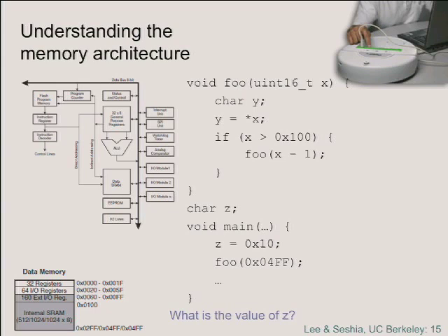We only have 1K of memory, though, in this architecture. And we've done a recursive call at least 100 times in hex, which is big enough to overwrite the memory. You're going to get a stack overflow. It's big enough, actually, to write to the I/O registers, too. This program probably won't even complete execution. It's going to start doing just crazy stuff. As soon as your stack exceeds where the program counter is stored, you're going to overwrite the program counter when you make a procedure call.